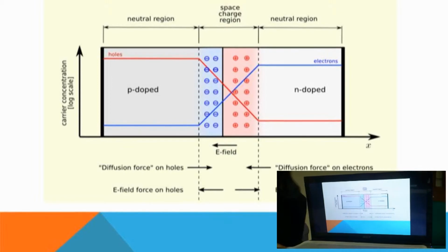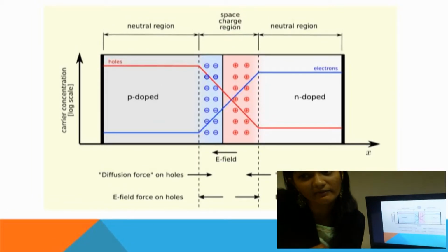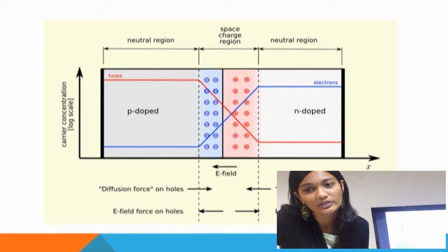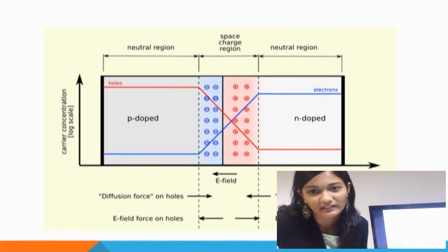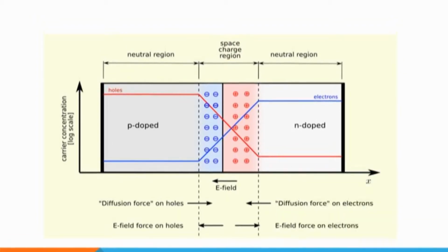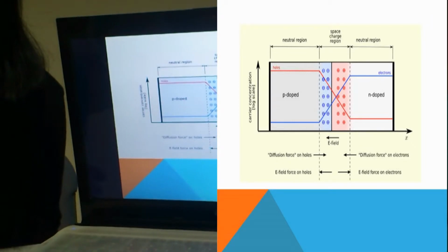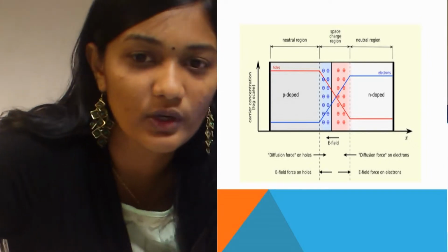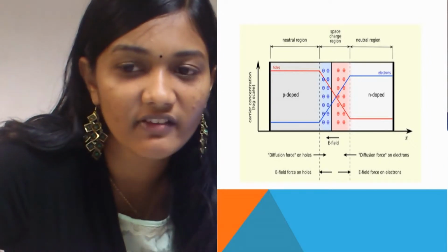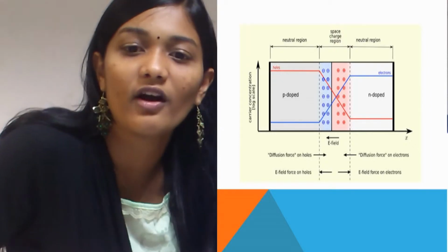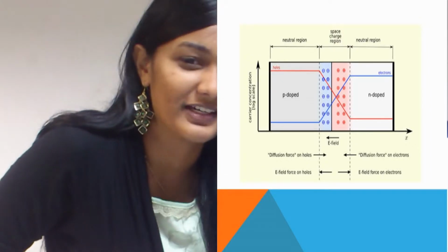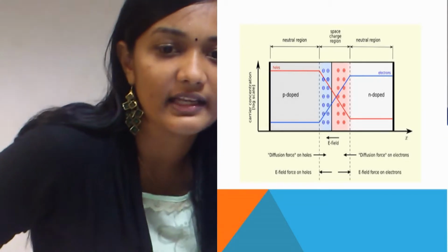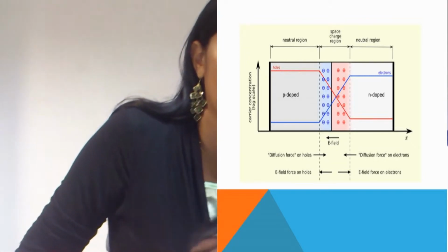By this figure, we can see a PN junction in thermal equilibrium with zero bias voltage applied. Electron and hole concentrations are reported respectively with blue and red lines. Gray regions are known as charge neutral, whereas the light red zone is positively charged and the blue zone is negatively charged. The electric field is shown on the bottom. The electrostatic force on electrons and holes and the direction in which the diffusion tends to move electrons and holes.